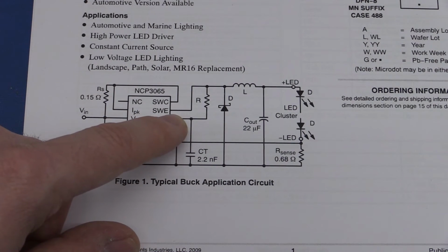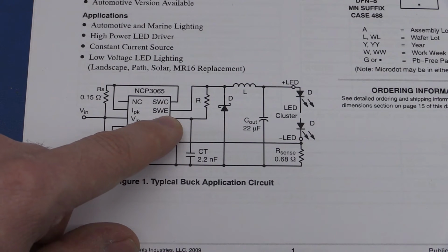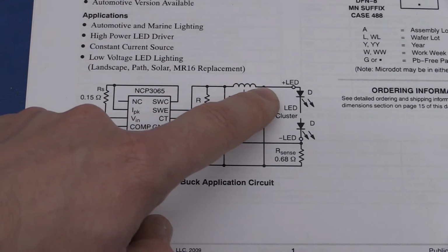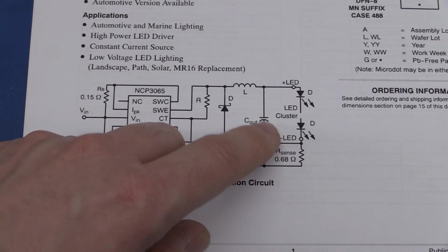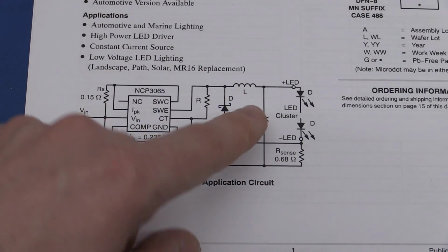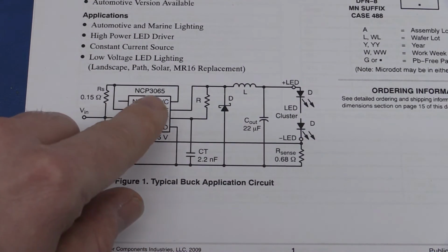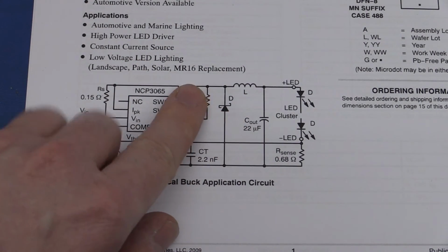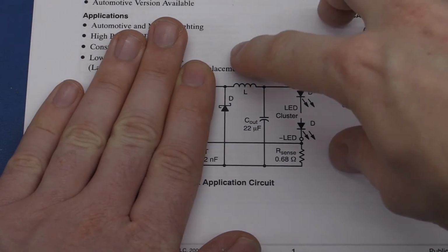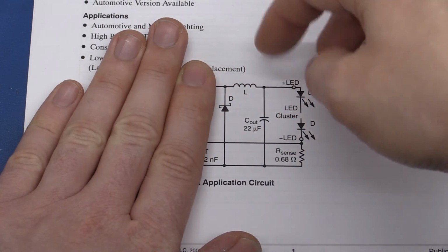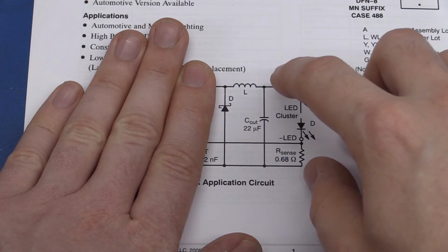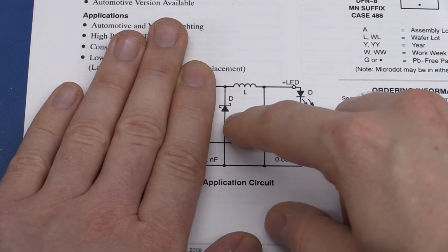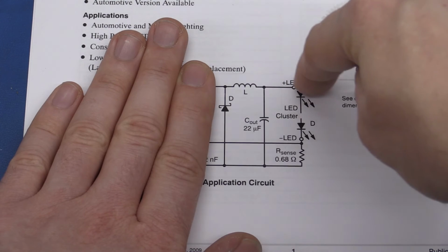You have your transistor inside the chip, and it turns on or off the SW. When it's on, it pushes current through the inductor and pushes current through the LEDs. If you don't have the capacitor, then it just pushes current through the LEDs. When it turns off, the inductor still wants to push current forwards, and since this is off, the voltage here tries to go negative, because if a current is flowing, there has to be a potential difference. To complete the loop here, we put a reverse biased diode here, and the current can flow through the loop here.